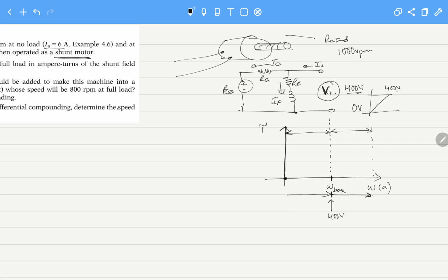So by increasing the voltage in a ramp, we can maintain the torque constant for the machine and vary the speed of the motor. And we know that P converted is torque times speed. So the speed of the motor will gradually change from 0, but torque will be fixed. If we look at the power consumed at this time, it will be a straight line increasing up to the rated power that the machine can withdraw. When it reaches this point, the base speed, which is the maximum rated speed written on the nameplate, we have performed this through the Vt control method.